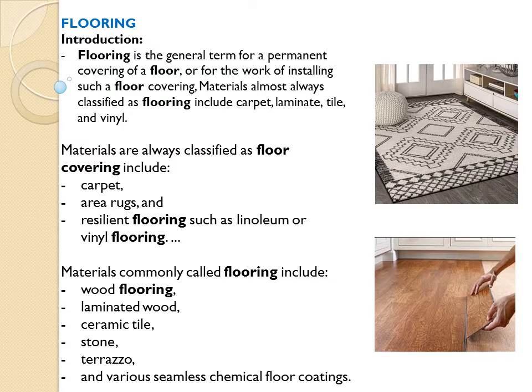Why is ceramic tile used as exterior? There are certain criteria, because the outcome of the tile is very rough. For outdoor spaces, smooth tile doesn't work. So to resist slippery conditions, ceramic kind of tiles are used.